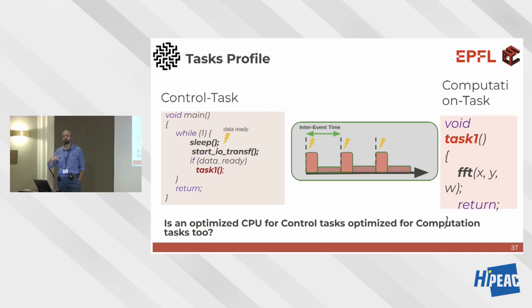If you are doing a system on chip and most of the time you have a dedicated accelerator to do data processing and your CPU is only there to do the task here on the left, controlling and orchestrating the SoC because the computation is done by the accelerator, then you want to go for this kind of CPU. Whereas if you are trying to do both these tasks and the computations on the same CPU because you don't have an accelerator, or because you want a cheaper, easier, smaller system on chip, whatever the reason, then of course within the profile you have to include that task.